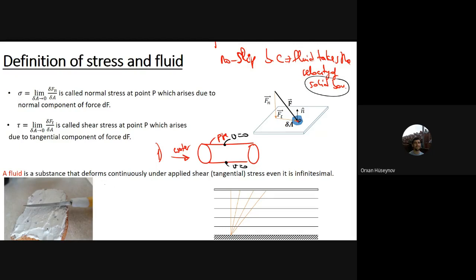I can give you another example. I have said it here. You move the knife in that direction with velocity of v, and the butter molecules or particles take the velocity of v at the boundary. These are v, but this one is another boundary, which is the bread, a solid boundary. When we say boundary, we mean solid. And here the velocity of the fluid particles is 0. So here fluid particles don't move because the solid boundary doesn't move, and here fluid particles move because the knife moves with velocity of v.